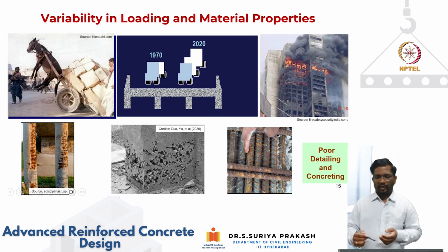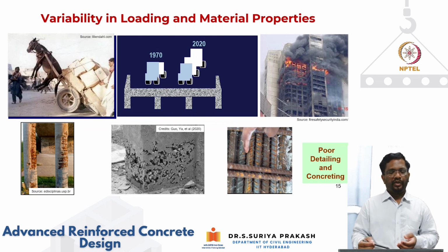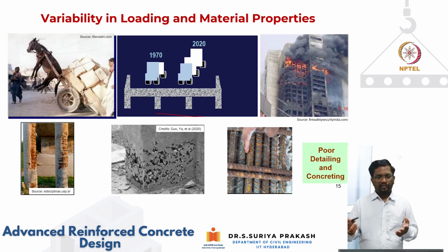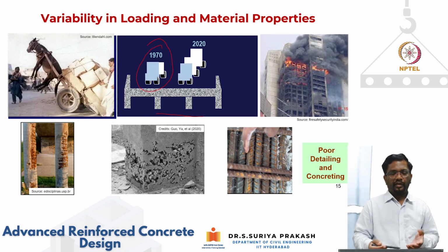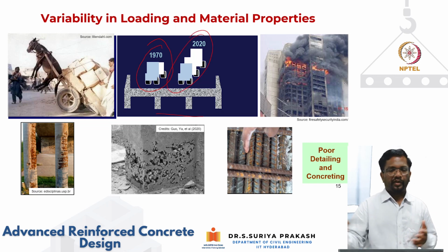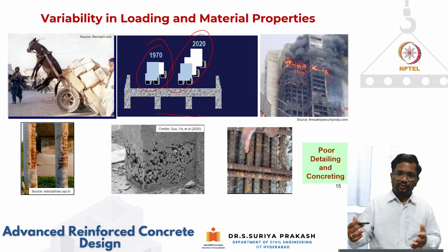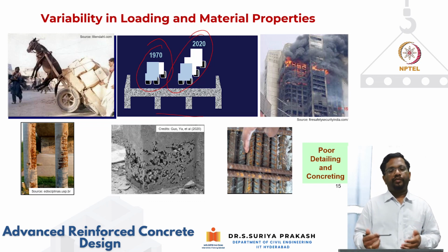So this is what I talked about. There's going to be a lot of variability in the loading that you're assuming, and you can see that in the traffic condition. If you're designing a bridge, bridges are usually designed for 100 years of service life. For bridges that were built in the 1970s, you can imagine the size of the trucks and the volume of traffic. And now in 2020, definitely the sizes of trucks have increased, the load distribution has changed, and the volume of traffic has also increased. So this variability in loading we need to consider in design.